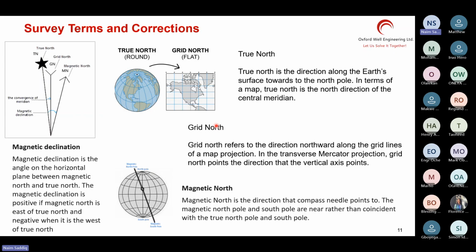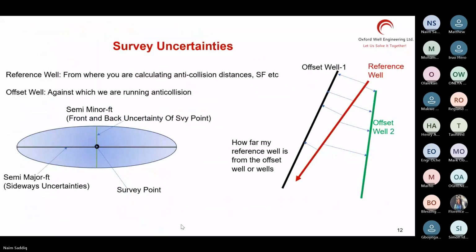It is for drilling, basically, the surveys, but you also use them for planning. Every time you take a survey, your azimuthal direction, your azimuth, could be slightly off from reality, because all measurements have errors. Surveys are not 100% correct.